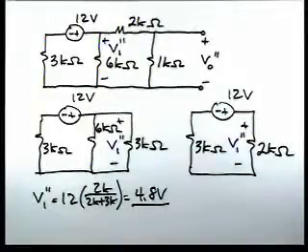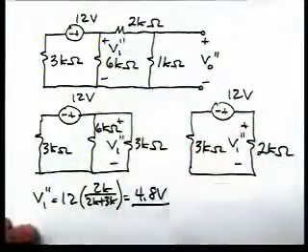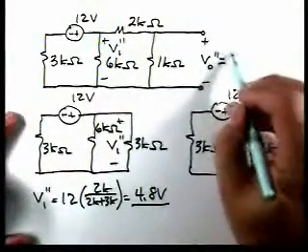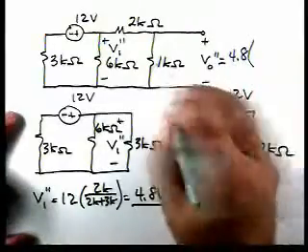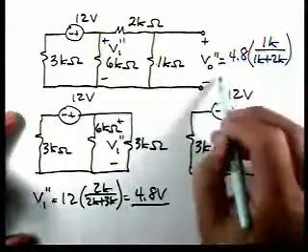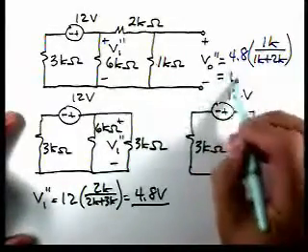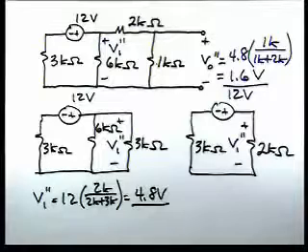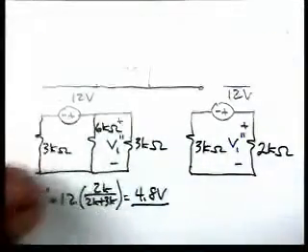Now, if we look, we have a voltage divider here. So V0 double prime can be found by voltage division. We have 4.8. We want the voltage here. We have 1K over 1K plus 2K. And that tells us that V0 double prime then is 1.6 volts. That leaves us one additional source to look at its contribution, and that's the last current source, a 2 milliamp source.